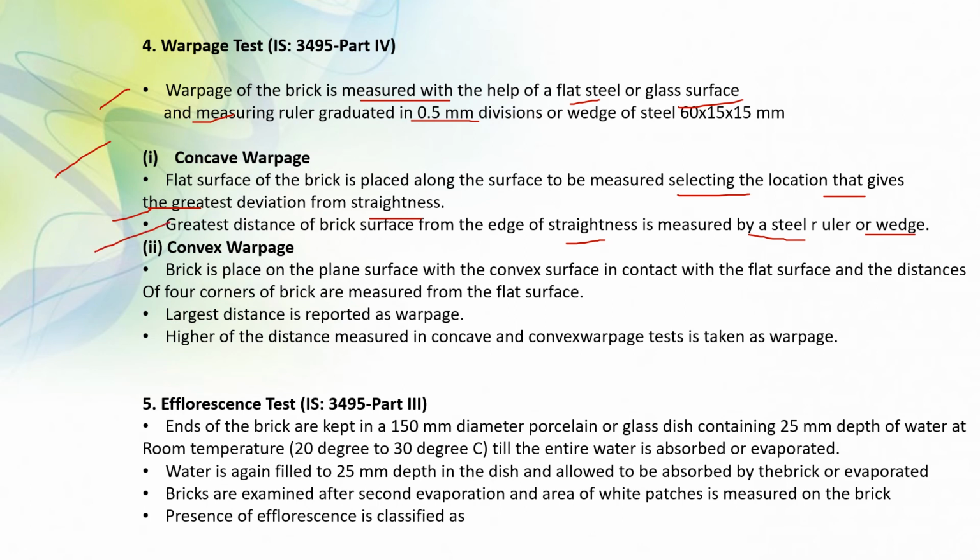Next, convex warpage. The brick is placed on the plane surface with the convex surface in contact with the flat surface, and the distances of the four corners of the brick are measured from the flat surface. The largest distance is reported as warpage. The higher of the distances measured in the concave and convex surface tests is taken as the warpage.